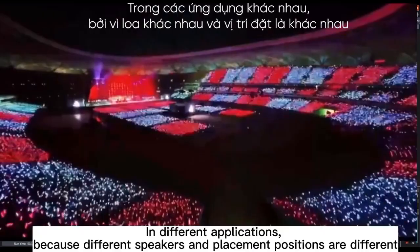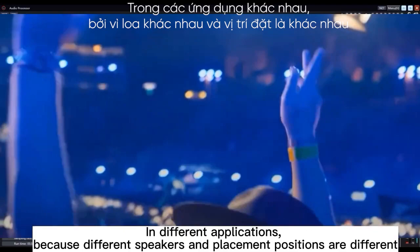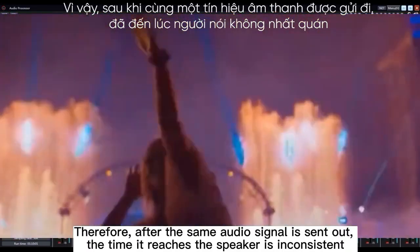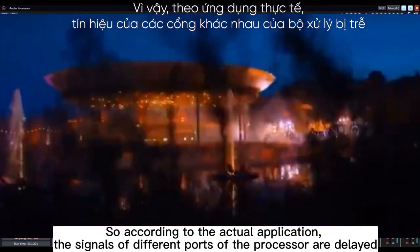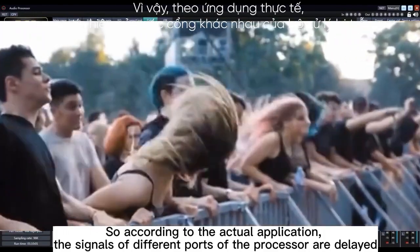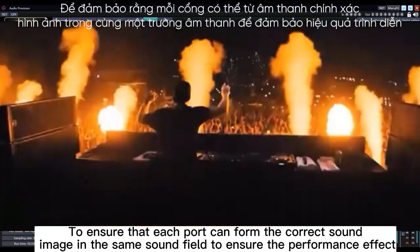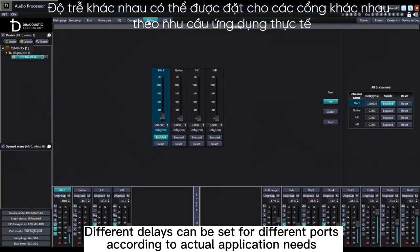This is delay setting in different applications, because different speakers and placement positions are different. Therefore, after the same audio signal is sent out, the time it reaches the speaker is inconsistent. So according to the actual application, the signals of different ports of the processor are delayed, to ensure that each port can form the correct sound image in the same sound field to ensure the performance effects. Different delays can be set for different ports, according to actual application needs.